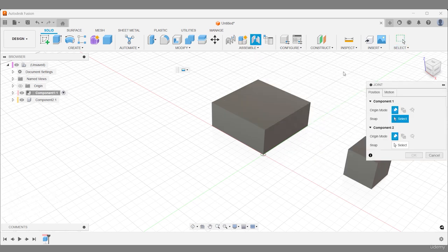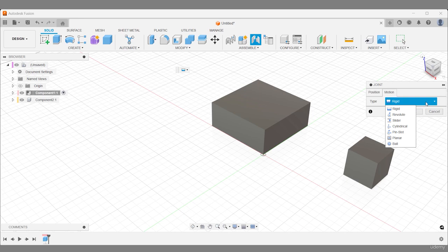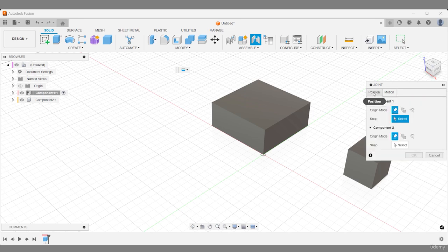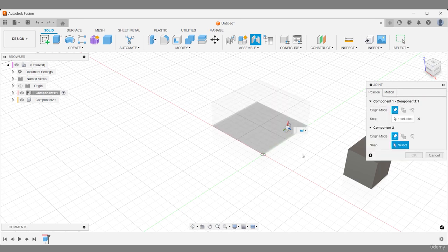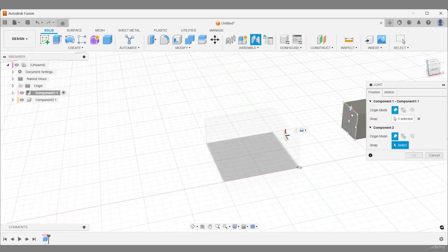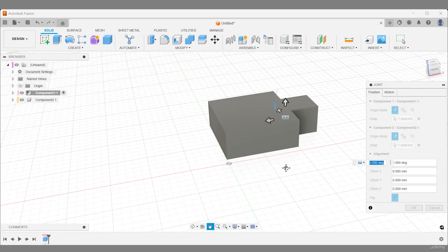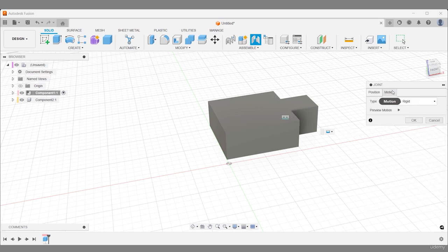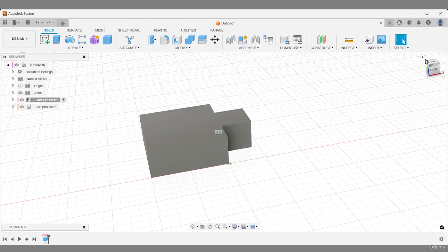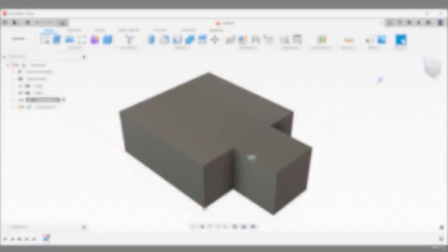The rigid joint type will lock your components together. This joint removes all degrees of freedom. Therefore, the options look a little different compared to joints with motion. A common scenario is a welded or bolted component. You want the components to stick together. The rigid joint has a vibrating simulation that, unlike other simulations, doesn't simulate the movement since the joint is rigid.